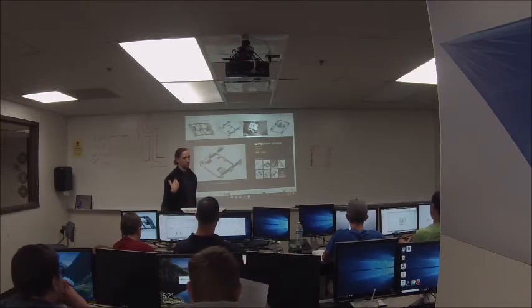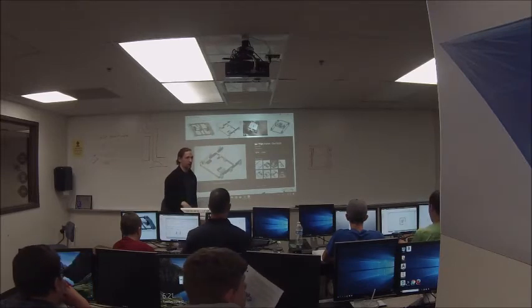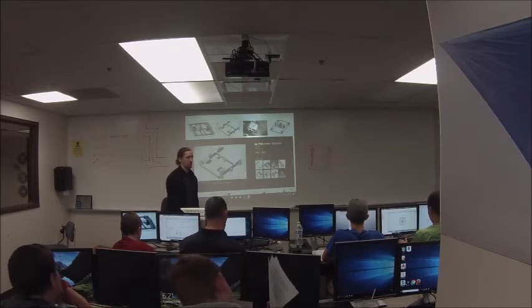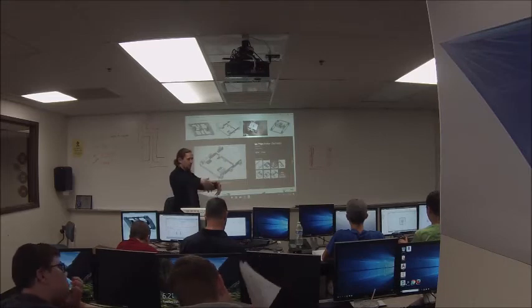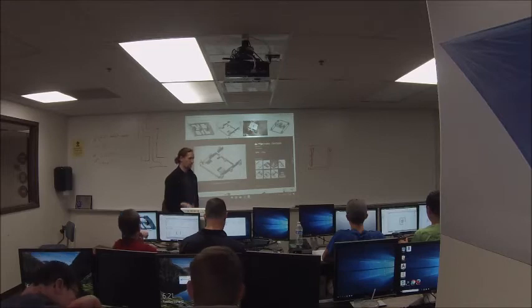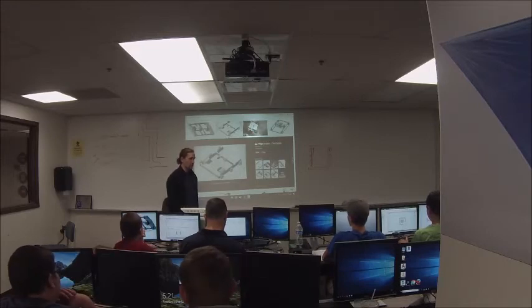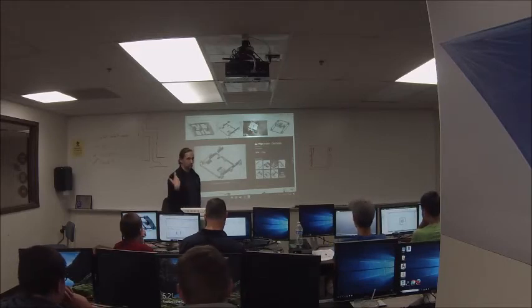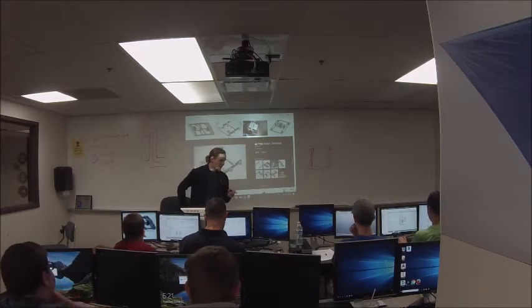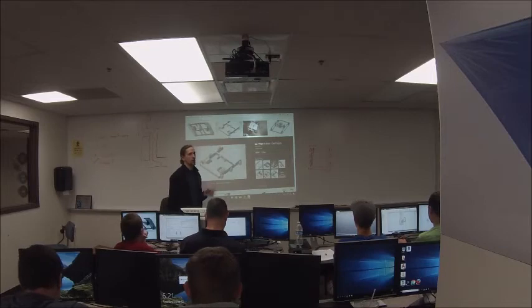That version is pretty much the simplest and cheapest way to do holonomic drive there is, but it's typically not very functional because you've got to get all the speeds right since they're at 45-degree angles. So it's typically not very smooth. It's difficult to program, difficult to drive, but it is very easy to build and very cheap. One other thing I didn't mention: H drive has a really hard time on a non-flat surface.